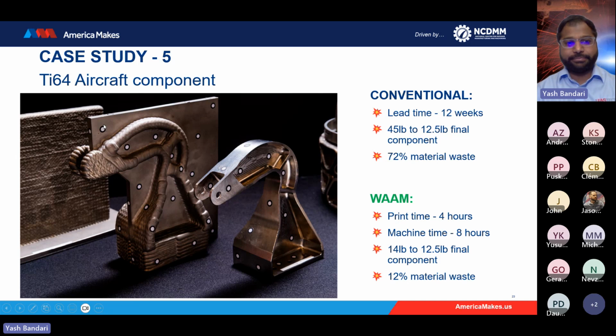we actually incorporated this build plate into the final component. Since we can do both 3 axis and 5 axis, rotating the tilted side table too, that is why we are able to print on either side, go back and forth after every layer so that the distortion is mitigated.